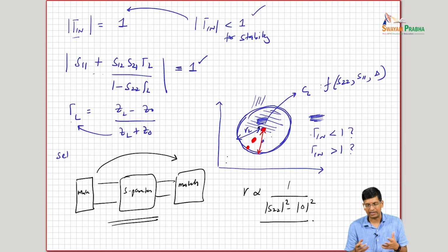So designing conditionally stable systems has to be done very carefully, to make sure that you are aware of what your actual ZS is and where it lies inside your source stability circle. So a similar concept exists on the load side, and you design for it.